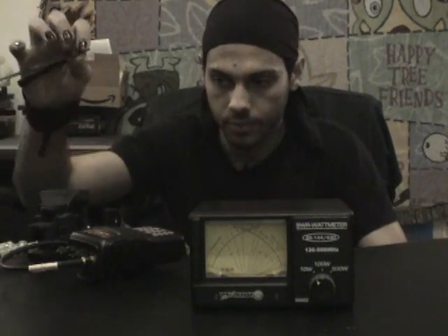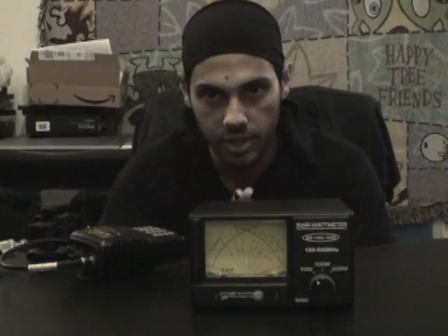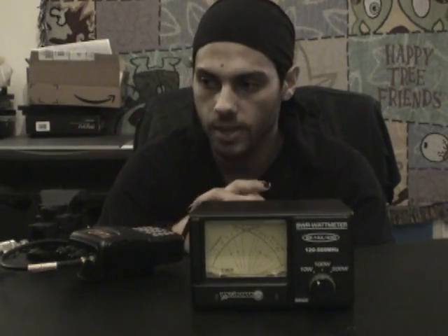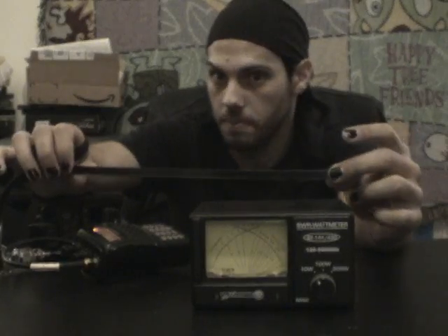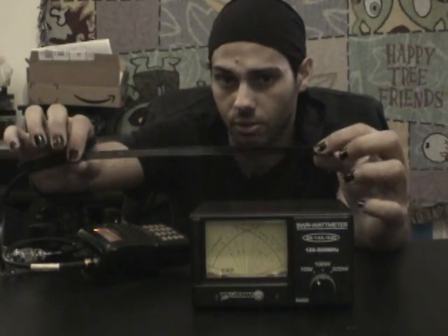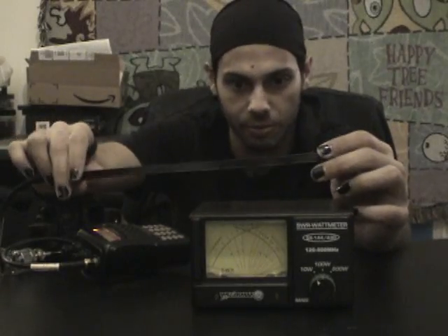Well, alright, gonna crouch down real quick, do a recap. So there's J-pole antennas, both ladder line as well as copper. You can use copper wire, copper pipe. The thicker the gauge wire or your pipe, the more power output you can push. With these little itty-bitty ladder lines, wouldn't go really above 10 watts maximum. I tell you the truth, I would push 5 watts and wouldn't even risk it above that.